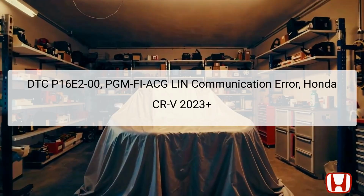The diagnostic trouble code, DTC P16E2-00, refers to a communication error within the Linear Integrated Network (LIN) system involving the Powertrain Control Module (PCM) and the alternator. This error typically occurs when the PCM cannot receive the essential signals from the alternator due to a disruption in the communication line.